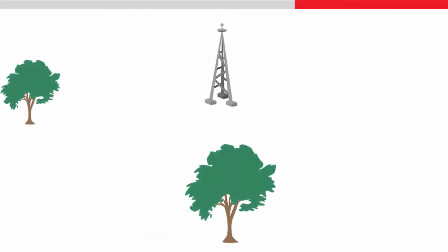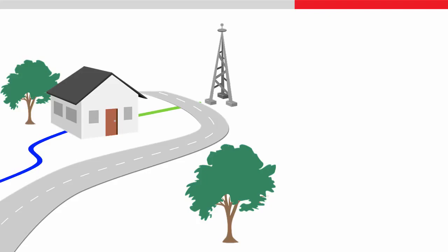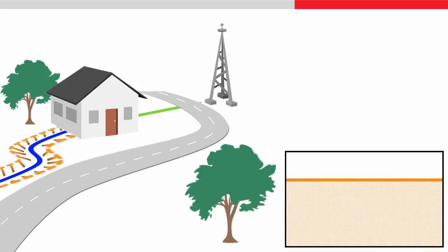We will use the example house project, where several different lines form a road, a building footprint, a service line, and a pipeline. Our task for this video is to stake the route of the pipeline and to mark where it is needed to dig slopes in order to lay the pipeline in a trench below the ground surface.